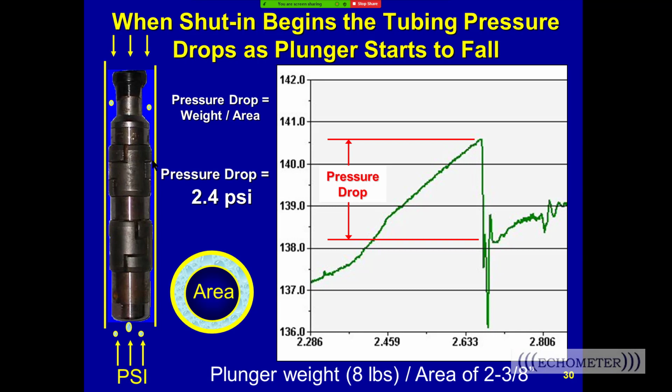The advantage is it's a shallow well. You can make quite a few cycles, and if you divide your cycles up into many cycles and you can still run your plunger, then I've seen casing pressures as low as 40 psi on a well that's 5,000 foot and work just fine.